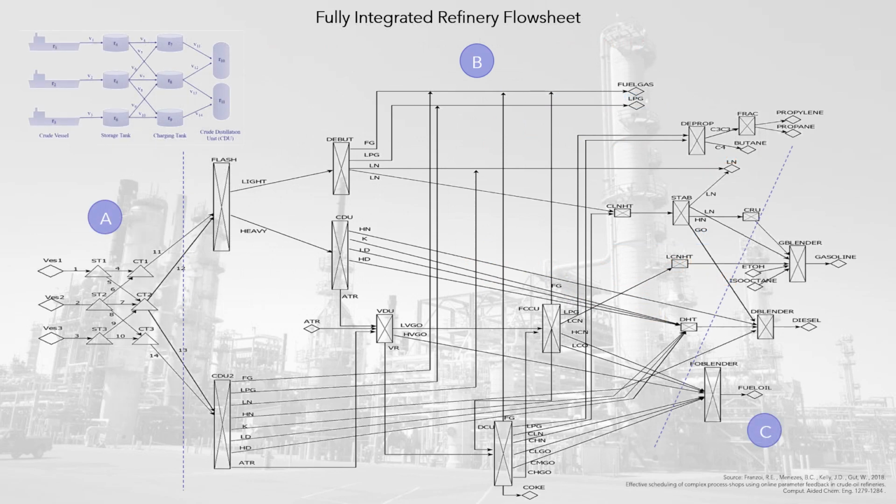The design of the refinery configuration is based on the figure. 3 raw materials, associated with 3 vessels, 3 storage tanks, and 3 cargo tanks, are the upstream operations for scheduling, Zone A. In Zone B, there are several process units such as hydrotreaters for light cracked naphtha, LCNHT, coker light naphtha, CLNHT, and diesel, DHT, fluidized catalytic cracking unit, FCCU, delayed coker unit, DCU, stabilizer unit, stabilizer, catalytic reforming unit, CRU, and delayed coker, DCU, are the downstream operations for planning.